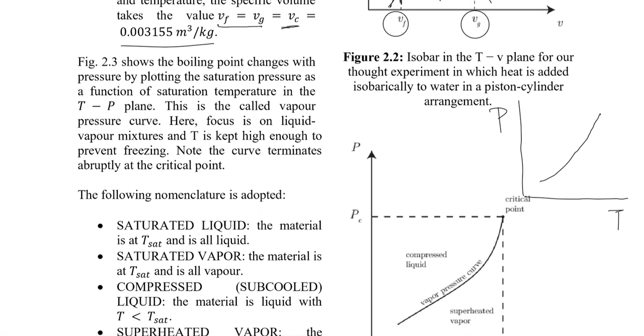So the graph of the PT would be somewhere like increasing the pressure would increase the temperature, increasing the saturation pressure would increase the saturation temperature. Now what does this graph actually say? If I've got 1 atm for the water, the temperature corresponding to that would be somewhere around 99.62. Now if I'm decreasing the pressure from 1 atm, the saturation temperature will decrease. Now if I'm increasing the pressure, the saturation temperature will also increase.